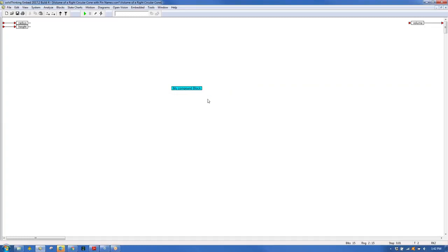Now, it didn't create any pins on it. So we can add those pins to it. If I go up here to the menu, you see right up here at the top these two selections, the plus and minus. I just click on the plus, bring this down and click on the left side. I'll add some pins to it. And I'll do the same thing on the right side. I'll add a pin to it. I can add a few pins to it. If I don't like them, I can remove them with the subtract arrow. Now, all that did was add pins. It didn't do anything internally. If I go inside, you see the pins are here, but they're not connected to anything.